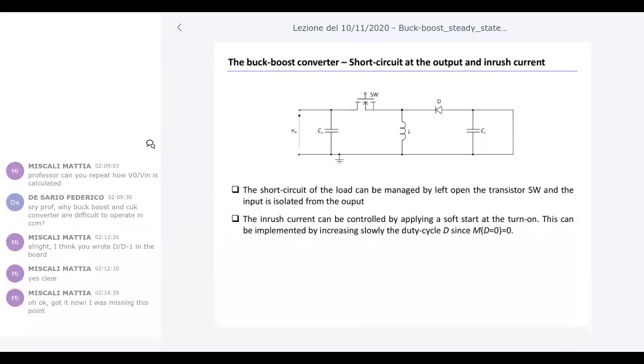Okay, buck-boost, CCM and DCM, classical analysis, which is in steady state. I just mentioned at the beginning of this discussion yesterday some of the benefits of having a switch in series with the power flow, okay? This is exactly what happens in the buck, for example. And it is not surprising that you have the same advantages here as in the buck, because the input side of the buck-boost is exactly that of the buck. So you have a switch in series with the current flow, in series with the power flow.